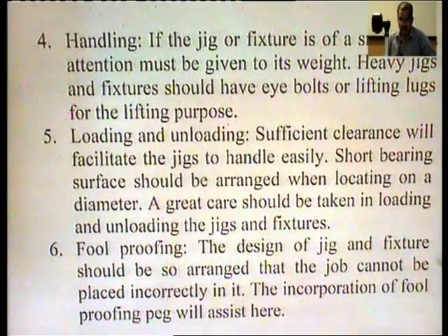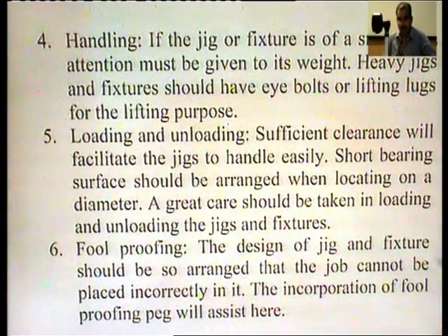Then comes handling. If the jig or fixture is of small size, attention must be given to its weight. Means, if the size of the jig or fixture is small, then it must have adequate weight, so that it can be easily handled. Heavy jigs and fixtures should have eye bolts or lifting lugs for lifting purposes.